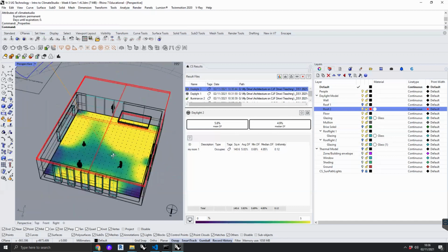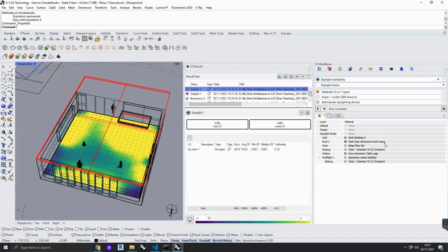Great. Okay. Are we happy with daylight factors? Make some sense? Great. And if you're into Design Builder, you can do much more. And I'm sure there's much more you can even do with this. For you, it'd be really interesting to think about different areas in your building and how much light they get. But anyway, there you go. So we can start pulling things around. Okay, that's daylight availability. Let's look at glare.